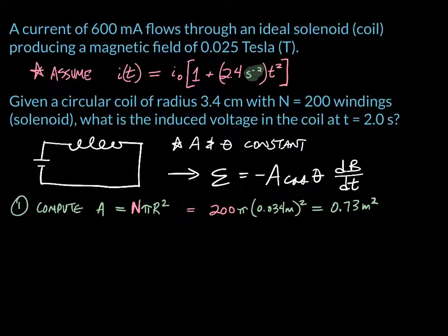So if you could cut each one of these 200 windings out and lay them out, they would be about 3/4 of a meter stick by 3/4 of whatever 0.73 square meters is. Roughly 3/4 of a square meter. Since the flux is going through all 200 of those loops, I have to multiply it by the number of loops that I have. More loops, more flux, because it's flux per loop, if you will. And every loop, as we saw in the simulation, gets more current flowing. More bang for the buck, if you will. All right? So we have one piece of the puzzle. Yay.